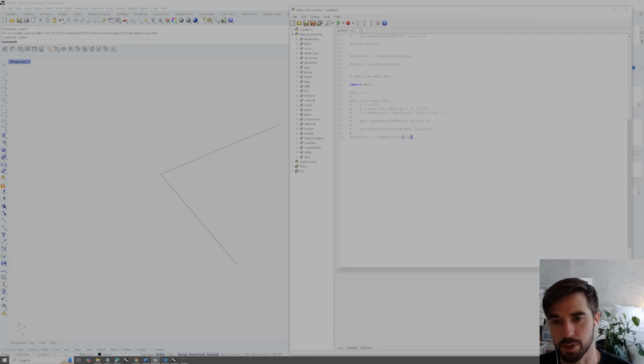So essentially what this means is that we have not just x, y, and z as variables, but we also have, kind of like we have here, a value like I. So I here is incrementing just based on the period of the math functions, so the sine function in this case. If we wanted to not just create one set of curves, but instead we wanted to create a surface structure, what we need is not just I, or we could think of that as maybe U, we also need a V direction, or a kind of V axis of the surface.